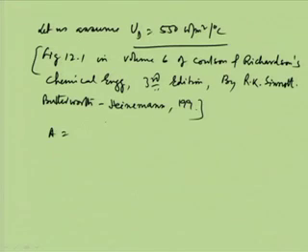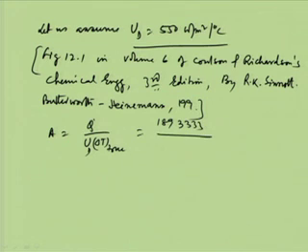So, once we know that UD value, then we can calculate the area of the heat exchanger. We know the heat load, that is Q divided by U into delta T true, which we have already got, and this U is nothing but the overall UD. So, it is 1893333 divided by 550 into 14.74, and that gives me 234 meters square. So, this has become the area of the heat exchanger, and this area is coming from the tubes.